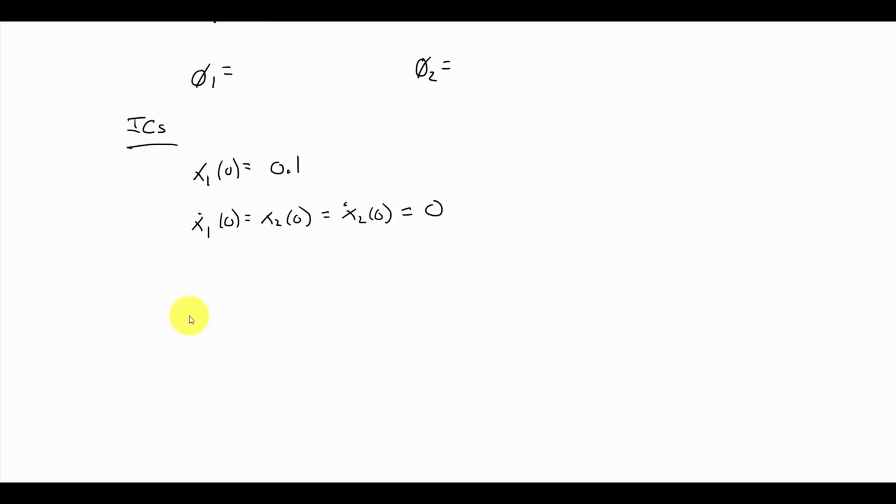We're going to put these initial conditions into our vector here. So we want x of t, although we want this at 0, is going to be 0.1, 0. So this is a vector expression. It is c1 chi1, we know that vector already, cosine omega 1 times t, which actually goes to 0, so that's just cosine of phi1, plus c2 chi2, we already know chi2, cosine of phi2.